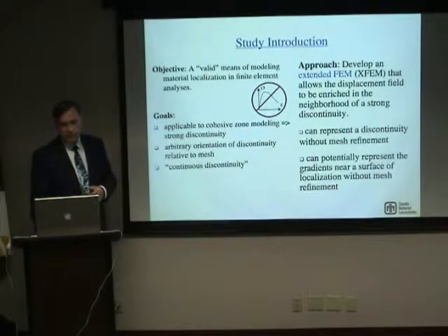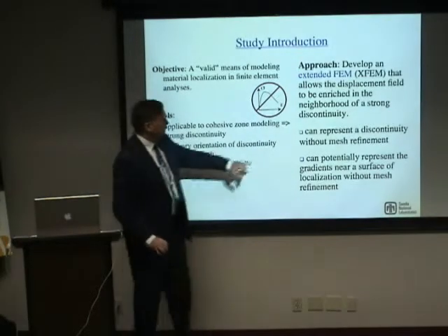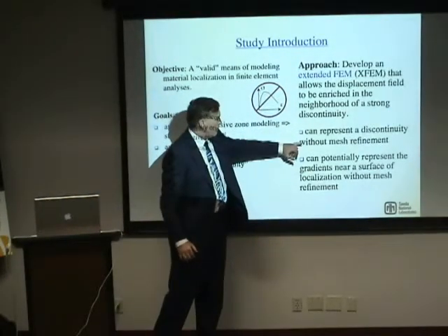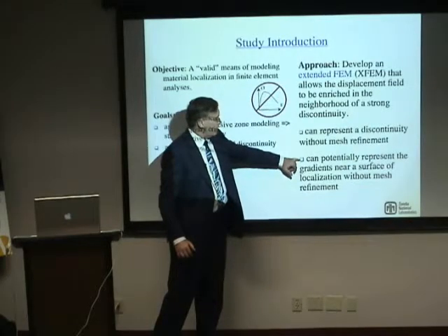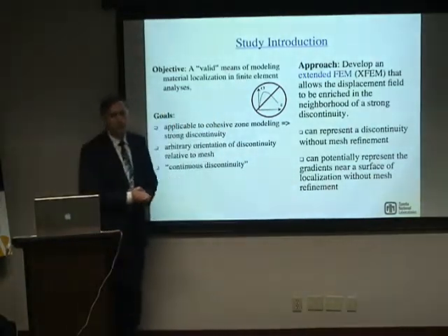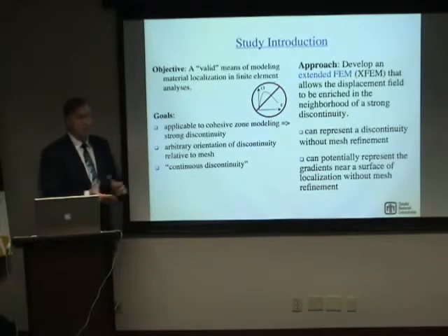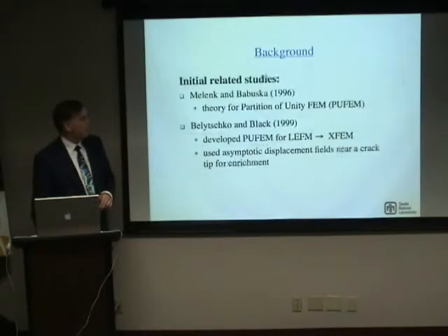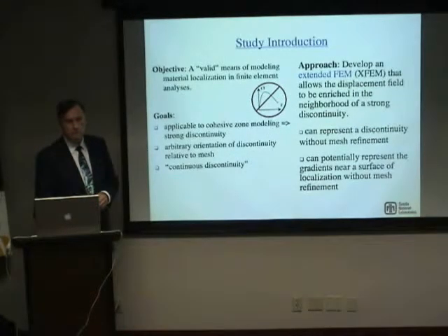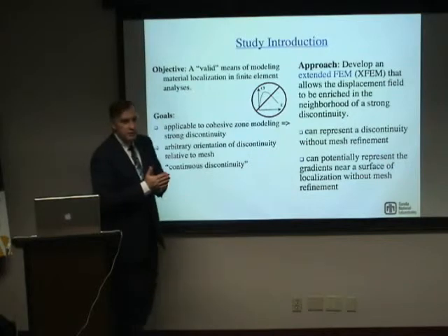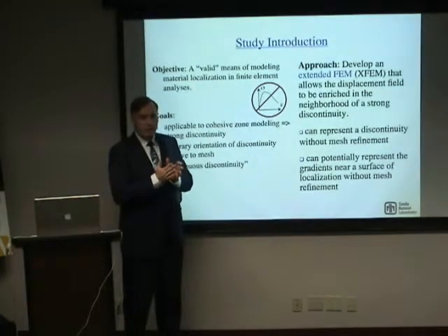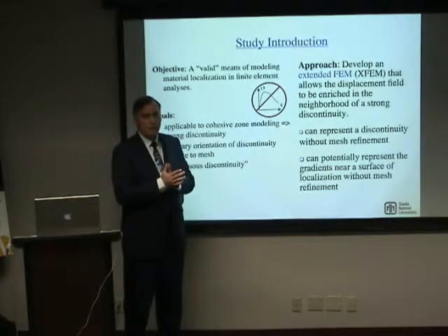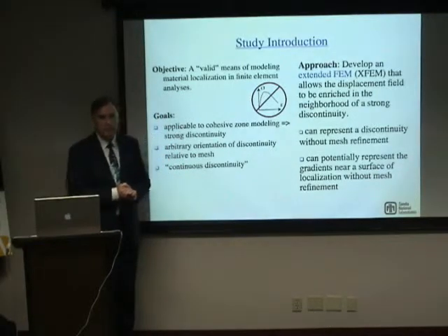Now, I'll mention Heaviside enrichment in a minute, and typically you can obtain this with Heaviside enrichment, but you're left trying to represent the gradients around the crack just by increasing the mesh density enough to pick it up with the polynomial functions. What you mean by discontinuity here is different from the standard crack, so it's a cohesive crack. Yes, it's a discontinuity in displacement though, except that, you're right, in the region where we say the crack is cohesive, we do have bridging across that with tractions. But it is still a discontinuity in the displacement field.